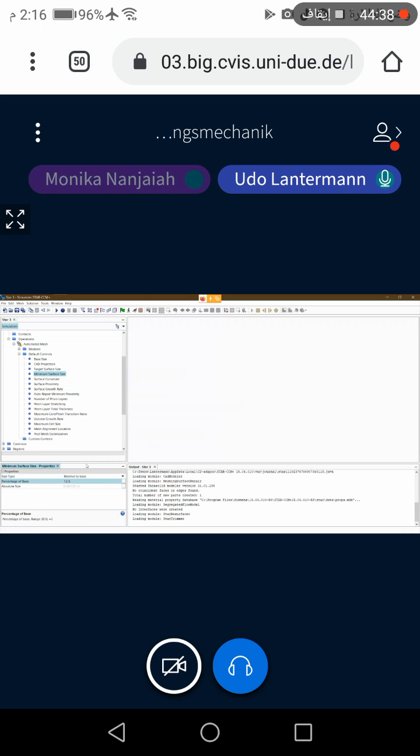The next refinement will be 25%, so we get 4 cells instead of the 1 of the first level of the base size. And the next refinement will be 12.5, which means we get 8 cells instead of the 1 of the base size. Every refinement is done by a factor of 2.